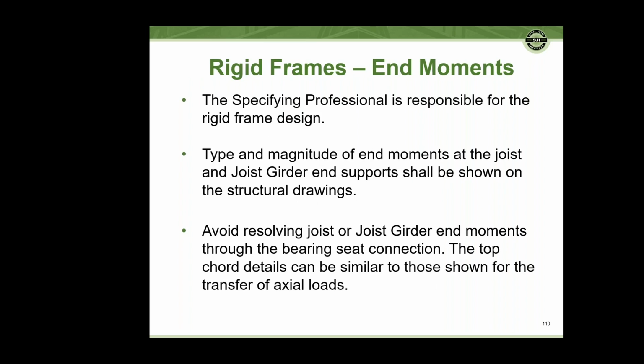Rigid frames, end moments. The specifying professional is responsible for the rigid frame design. The type and magnitude of end moments at the joist and joist girder end supports shall be shown on the structural drawings. Avoid resolving joist or joist girder end moments through the bearing seat connection.